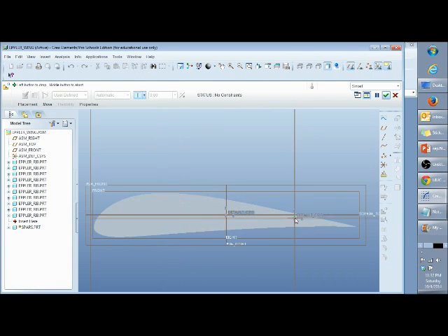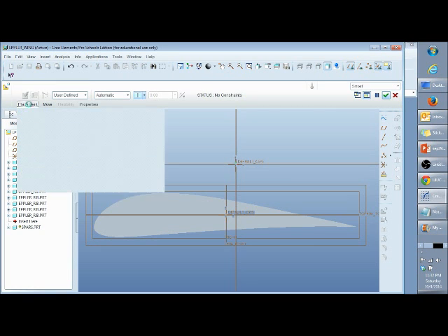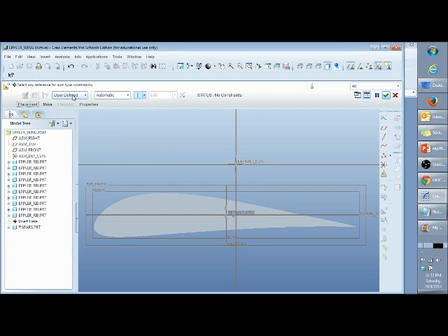And so now we can create the... Oh, now it's asking you to align stuff. So what I'm going to do is align the... I'm blanking out right here. Oh, datum points. Not datum points, coordinate systems. So I'm going to select this default system, which is the coordinate system for the part that I'm creating, and then select the assembly coordinate system. And hit OK.